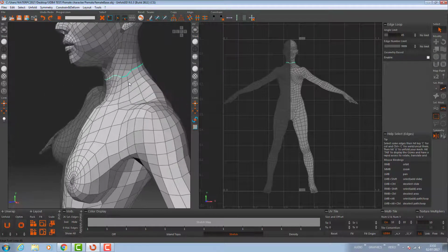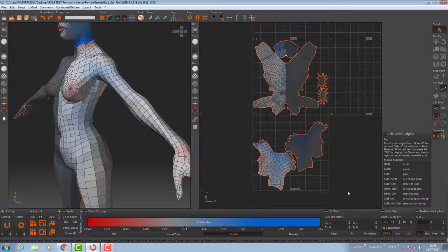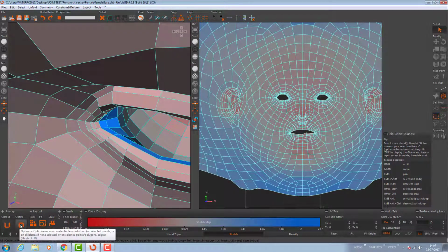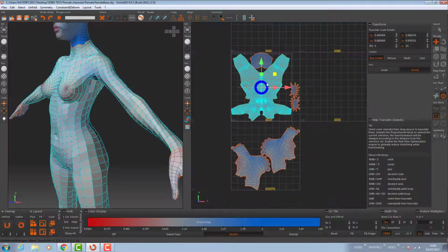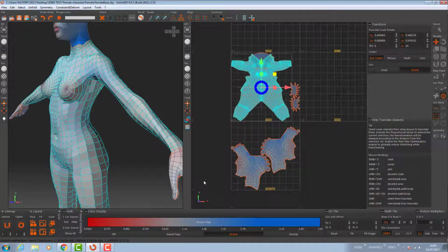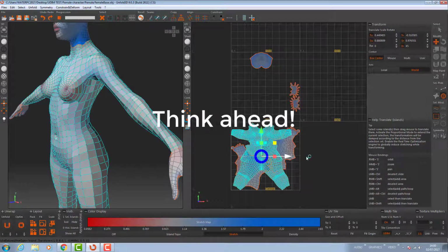Once we have the seam selected, we would use a cut tool, then the unwrap tool. The unwrap tool would then try to work out the best way to flat pack the 3D model by its inbuilt algorithm. Once we do this, we can then use the relax tool to get a better unpack to become more even and distributed. We can then orient the pieces, scale and place them where we desire within the designated tile or the UV space.